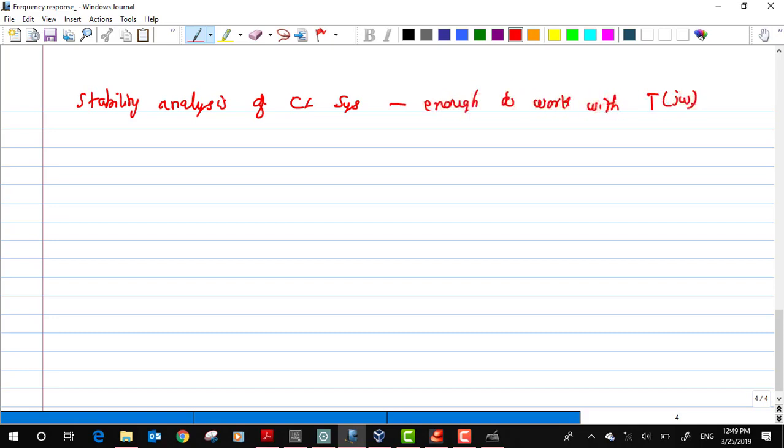So this is one of the important statements that I would make. If I want to analyze whether the system is stable or not, it is not the open loop gain or the closed loop gain that I'm really looking at, but the loop gain. I will use the letters LG. So LG is nothing but the product of beta times the open loop system gain.